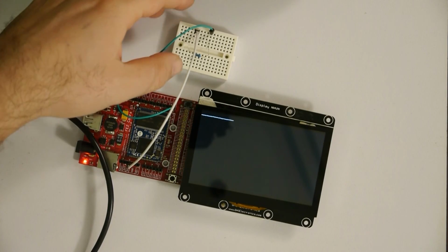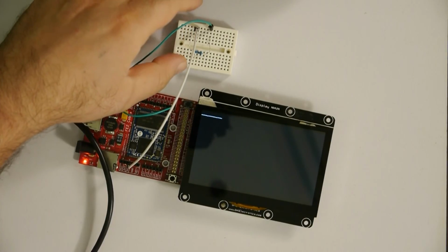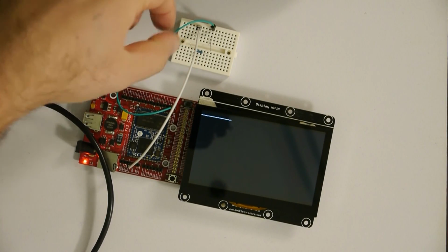I have this resistor. This is like a 1 mega ohm. It's a very large resistor. A smaller resistor would make it, considering the capacitance I have is extremely small, I don't even have a capacitor. This is the capacitance of the pin itself. So considering this is really small, I used a very, very large resistor so this will take some amount of time that I can measure in my code. This is about 1 mega ohm. That's connected between the pin and ground.